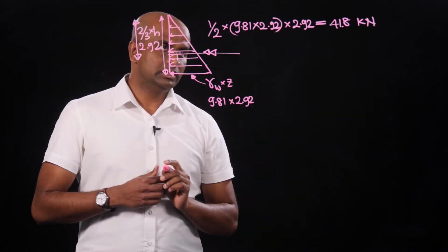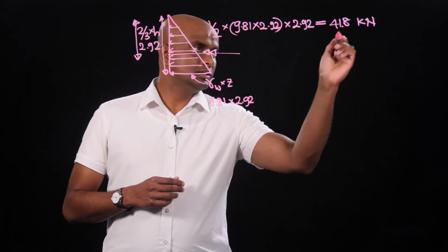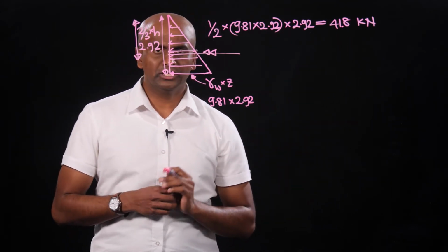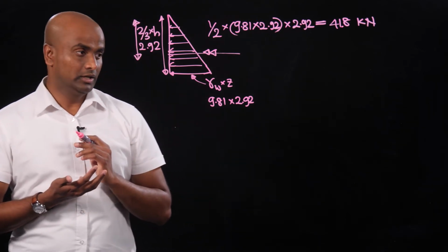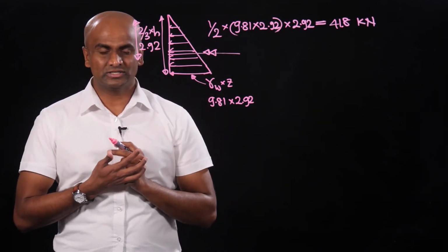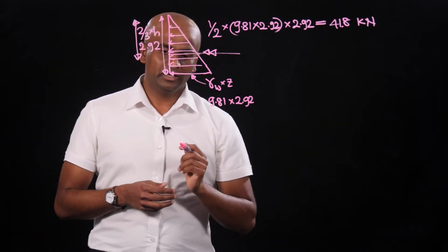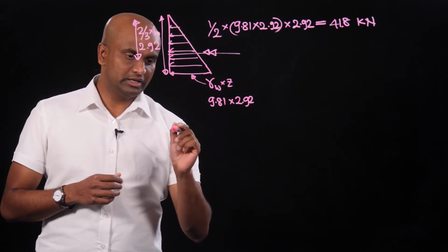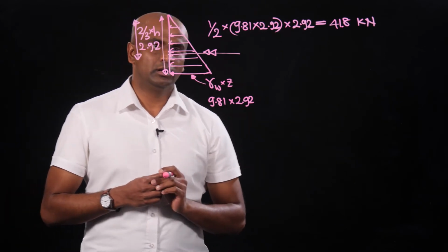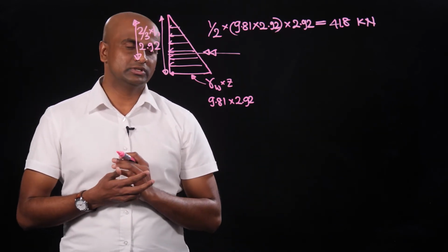Now we know the additional pressure that should be accounted for in this case. And the other point here is, since under this condition the slope is not submerged, we will have to use the saturated unit weight. And now we can calculate the total disturbing moment and also the resisting moment.